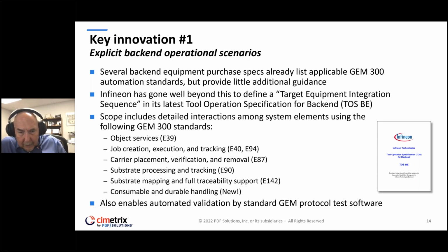So the E39 object services, dealing with control jobs and process jobs for E40 and E94, handling carriers, not just of FOUPs or cassettes, but all the varieties of carriers that you have in the back end, some of which I mentioned a few minutes ago. Substrate processing and tracking, and again, a substrate here is not necessarily just a wafer or a single device. You'll see in Brian's slides what the range of substrates is that has to be handled. And then finally, a new topic for which there is not yet a SEMI standard, but which we're working on, is a standard to actually track consumables and durables.